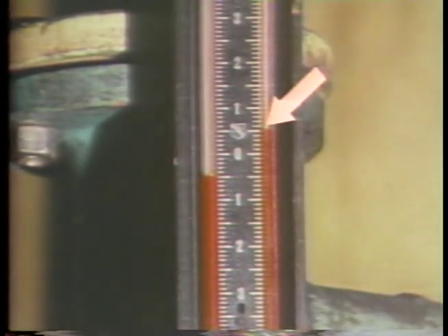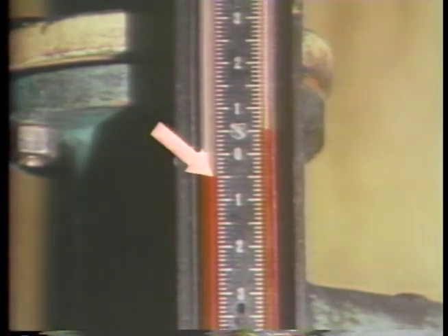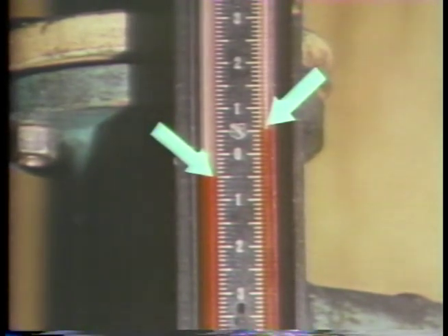In the case of this example, one end of the column of water, the one above 0, reads about 1/2, and the other end of the column, the one below 0, reads about 1/2 as well. Both readings above and below 0 should be the same. Otherwise, there isn't enough liquid in the manometer and the readings won't be accurate. To determine the height of the column supported by the pressure, we add both readings above and below 0, and we get 1 inch of water.